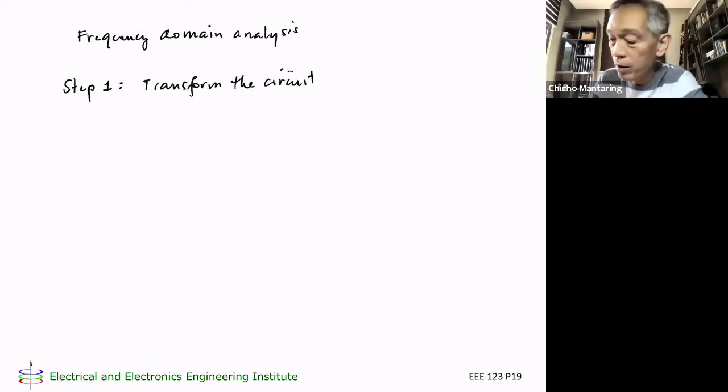Your sinusoidal sources, you transform to phasors. Your passive elements, you transform to impedances.